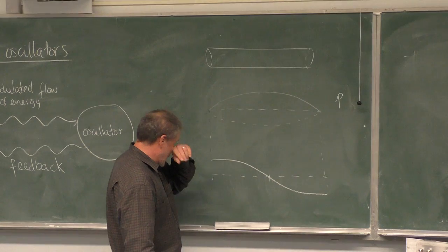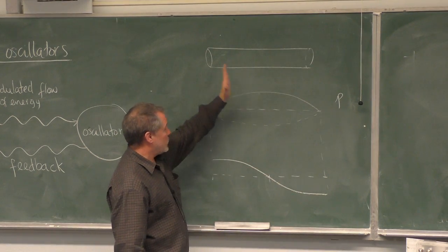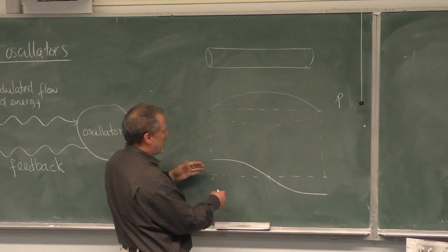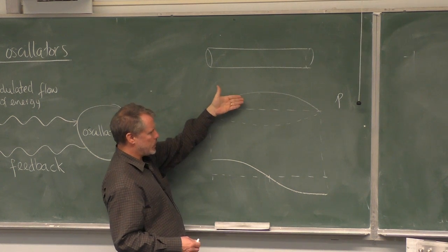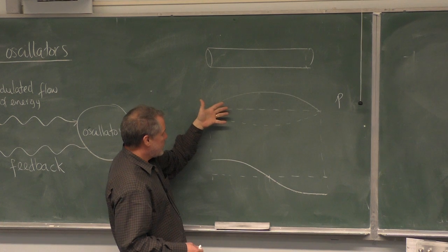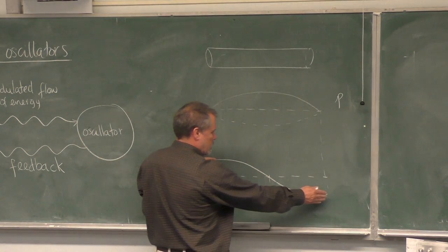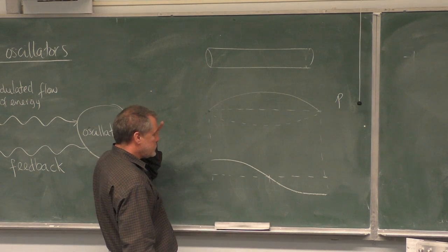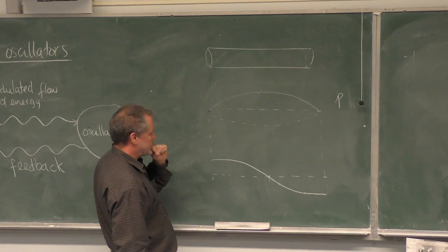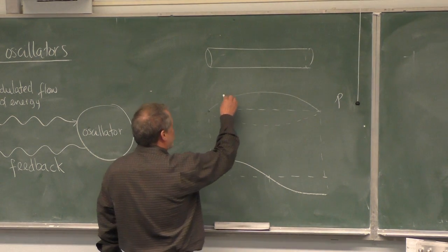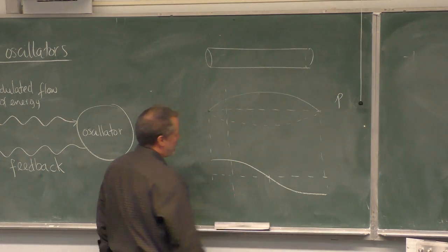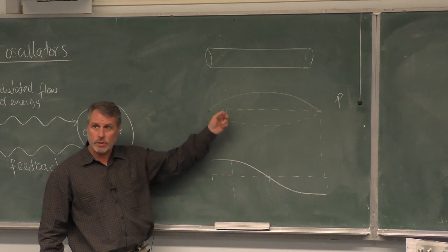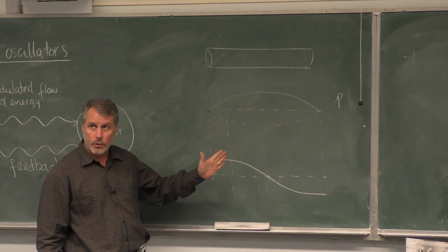The gas velocity is oscillating everywhere in the pipe, and there is a phase relationship between the two ends. Obviously, the phase in here is 180 relative to that one. Okay, so what else? If I pick a spot on the pipe somewhere there, I have both pressure and velocity swings. They are oscillating, both of them, back and forth.